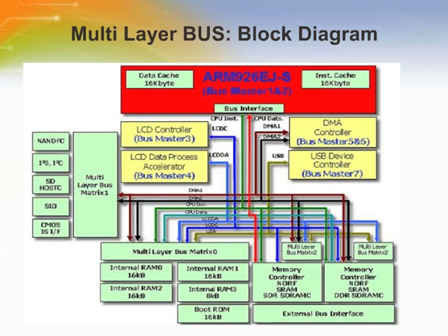The TMPA910 device has a multi-layered bus architecture. The new TMPA910CRAXBG has a CMOS image sensor interface that simplifies the implementation of applications requiring image capture. A touchscreen interface further reduces the need for external components in man-machine interface designs. Additional connectivity includes SPI, UART, I2C, I2S, and high-speed USB device, 480 megabits per second functionality.